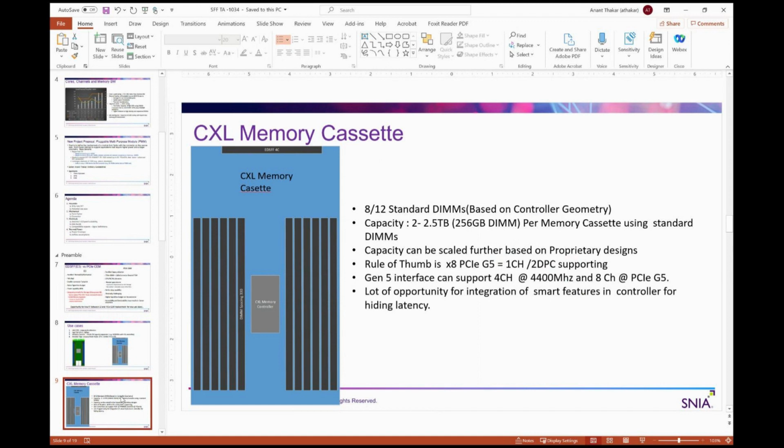And do you think we need any modifications to the EDSFF in terms of signaling to support the memory controller, or can we just leverage whatever connectors we have? So you could basically design using the standard, currently x16, which is defined on the EDSFF E3.L, or you say I need more IO capacity, correct? Let's say you want to go x32 or 2 x16 CXL channels. You should be able to handle that.